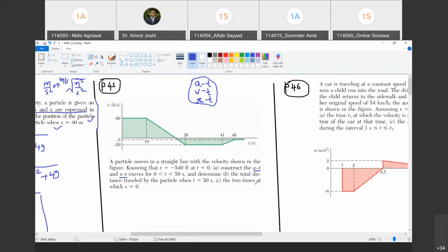Now, tell me, you have to understand one thing. These velocity time diagram, acceleration time diagram, and position time diagrams can look nonlinear, but they are describing the motion of a particle along a straight line, because these are not path diagrams. These are diagrams of evolution of velocity, acceleration, and displacement as a function of time, not as a function of position. Are you with me? Yes, sir. So these diagrams may be non-linear in nature, but essentially the particle is moving along a straight line. So it is exhibiting a rectilinear motion.